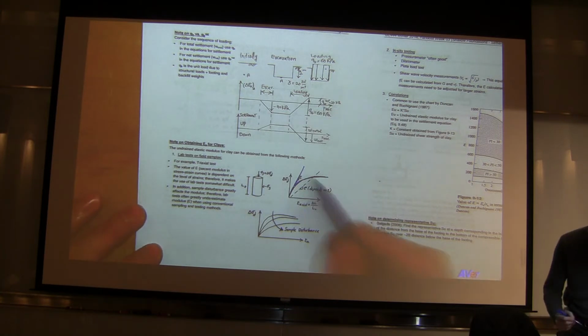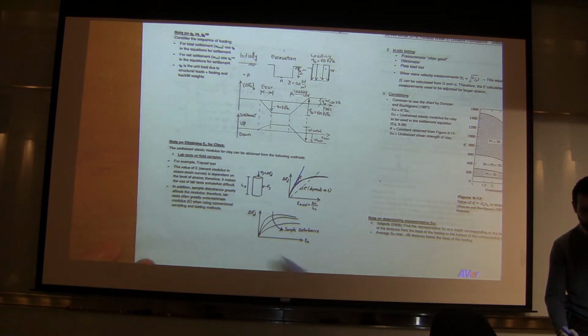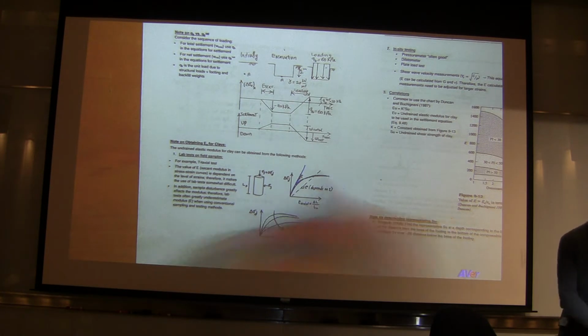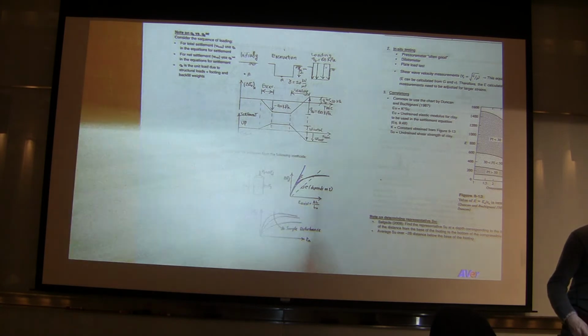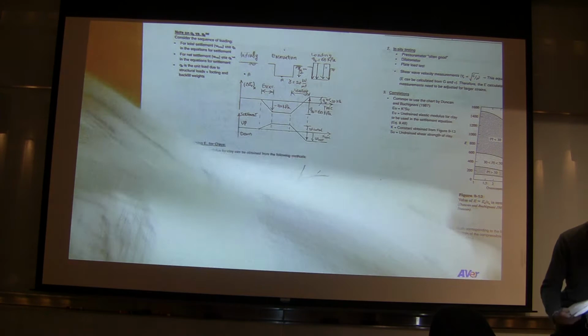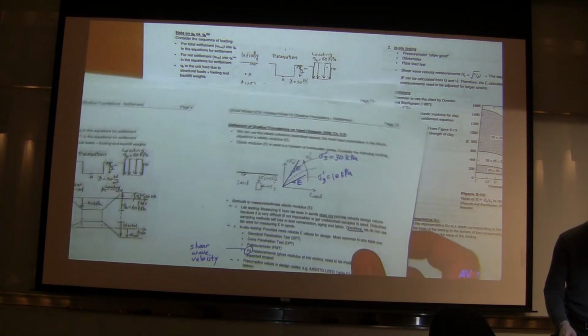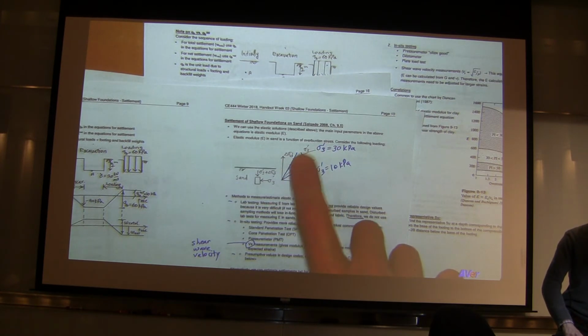And then there's another complexity to deal with. So again, for sand, we had this complexity that it was stress dependent. So depending on what stress the soil is under, the curve was different. And basically referring to, let's see which page that was. Here. So on page 10, we talked about how different sigma prime v for sand will result in different curves.